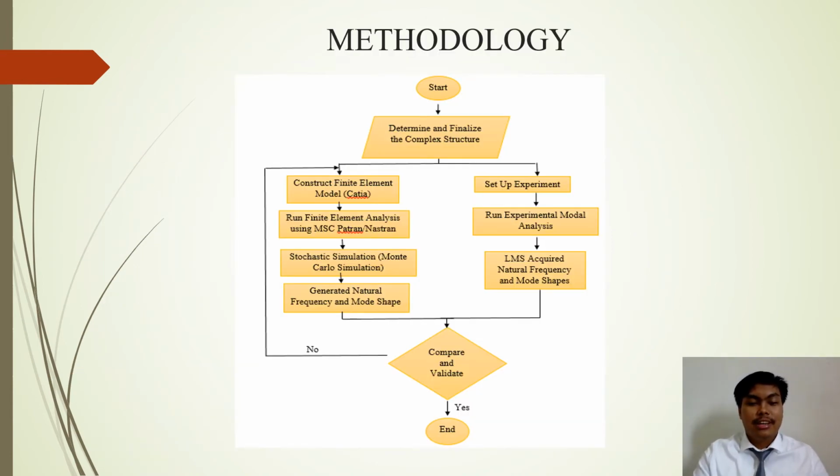Next, methodology. The process flowchart here shows the start to end process, where it determines and finalizes the complex structure, then moves to experimental modal analysis where the experiment is set up, and run the experiment where LMS acquired the natural frequency and mode shape. On the finite element analysis, I constructed the model, then run the finite element analysis using MSC Patran and Nastran, then use stochastic simulation, which is Monte Carlo simulation, to improve the accuracy of the results, and the generated natural frequency and mode shape will be compared to the experimental modal result to validate it.